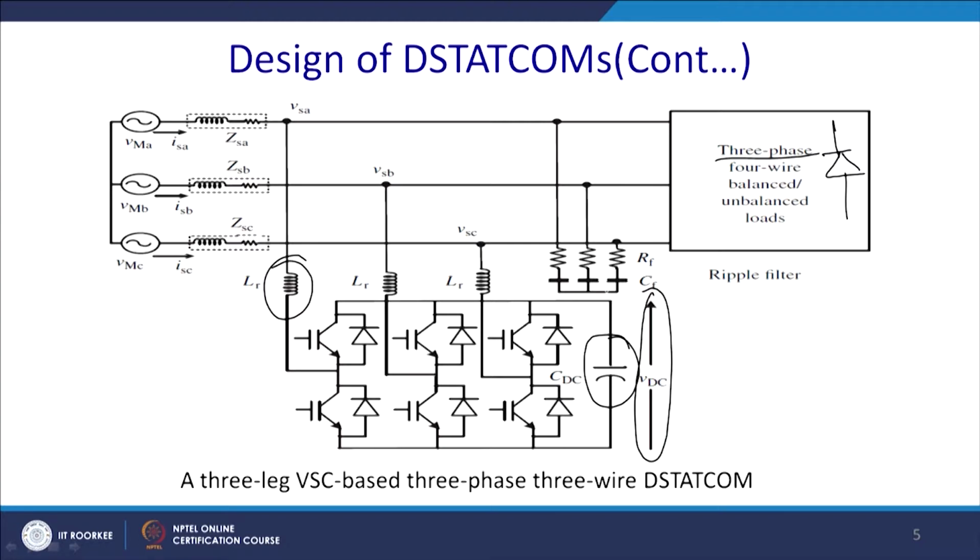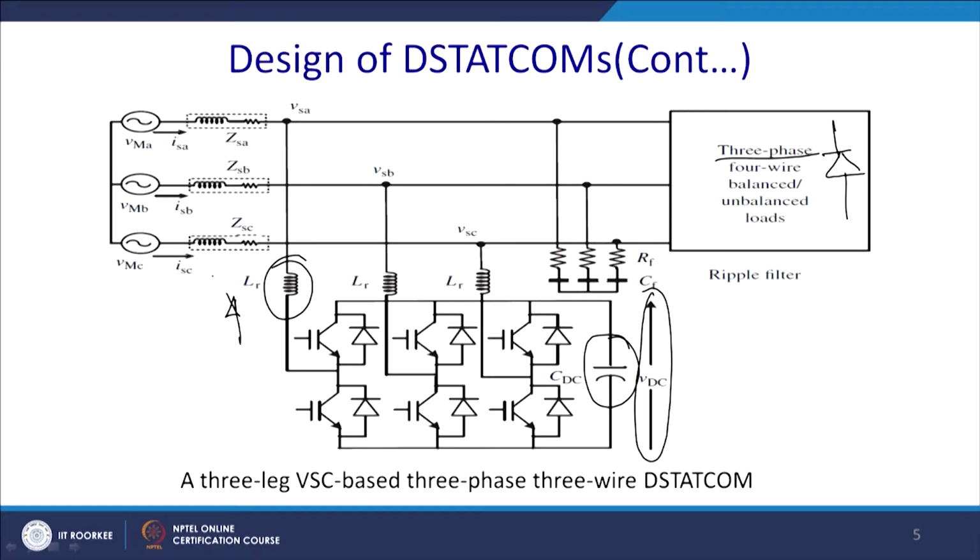Please note that since we have seen in the case of the STATCOM that it is required to inject power, the current has to flow this way. So, for this reason the DC link voltage has to be higher than the rectified DC bus voltage, because it is a 2 quadrant switch. Ultimately, due to the body diode, it will act as a rectifier, and it inherently sees a boost topology. When this lower switch is on, current will flow through this in the positive half cycle, and when the switch is off, current will flow through these directions, and thus it will boost the DC link voltage.